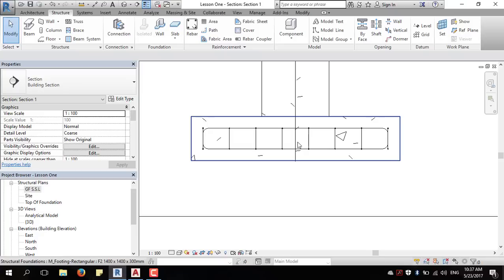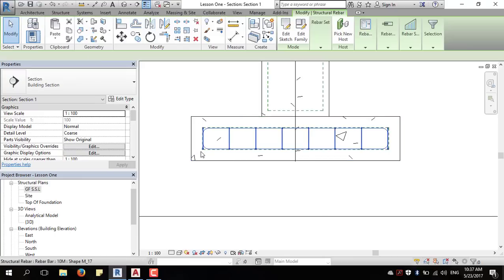It's called partition. For example, if you have a whole project, you will create a group for the foundation, a group for the tie beam. Also, for the tie beam, you will subdivide to views the columns. Also, a group of the columns like this. So I will choose all the rebars here.